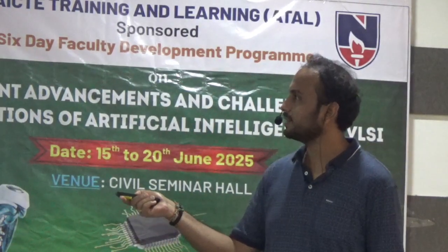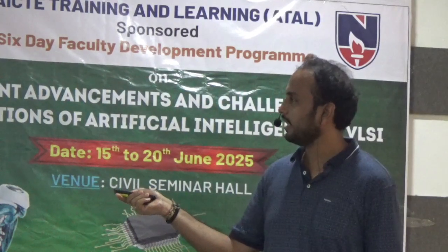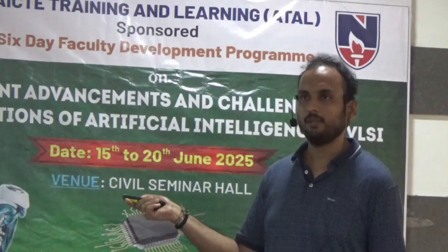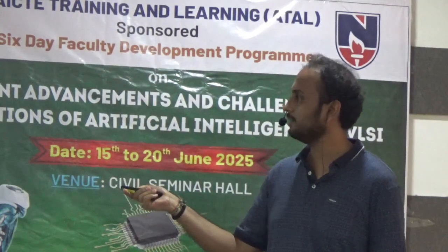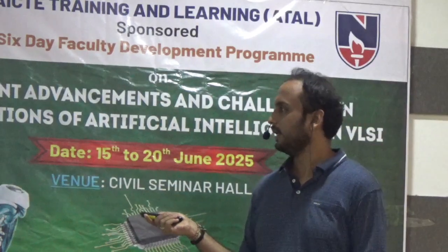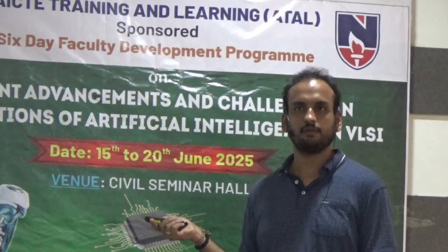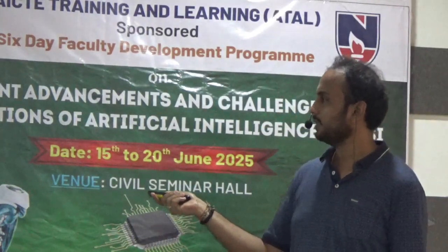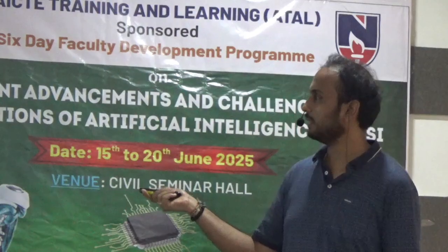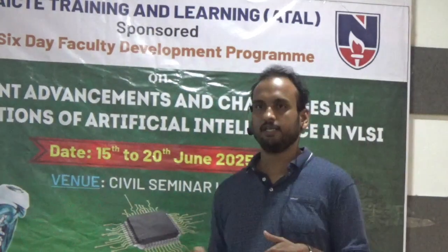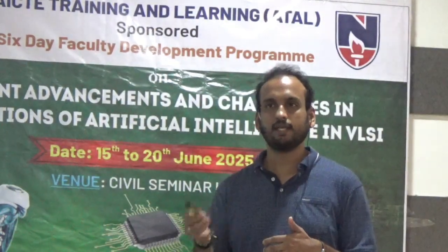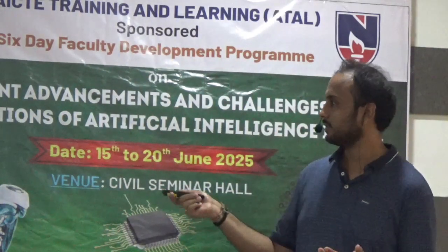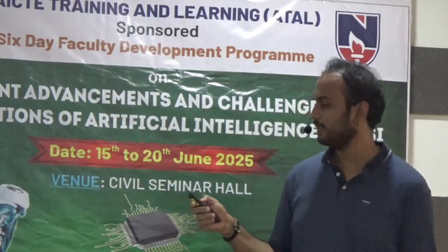And these are the different equations we plotted. This is the FT equation. With the longer channel devices, say 180 nanometer or 90 nanometer, FT is inversely proportional to L squared. When we go to velocity saturation, which is dominant in lower technology nodes, FT is inversely proportional to L. So rather than L squared, it becomes L. It means that if you scale down the technology beyond a point, you will not get that much improvement in FT. This is because of the velocity saturation effect.